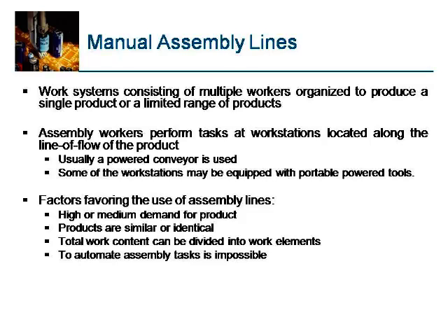Factors favoring use of assembly lines are high or medium demand of the product. You go for this kind of line when the demand of the product is very, very high and the assembly operation is simple. You cannot do the same thing for machine tool assembly. Machine tool assembly is not a simple task. The machine is kept at one point and assembly is done from all sides, and the total time taken for assembling a machine tool would be in weeks or months.